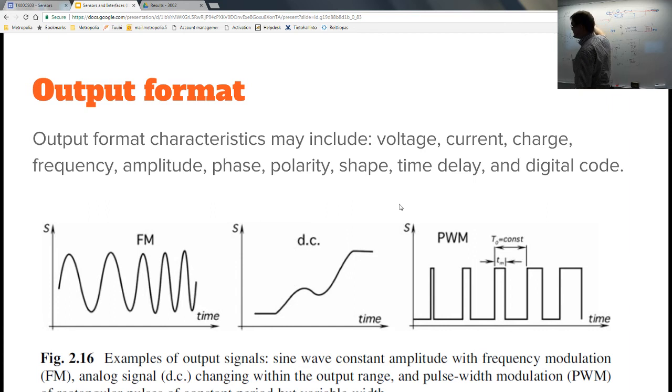And this is the way to do it cheap, since you can have these different capacitors for temperature, pressure, humidity, and then you have just a multiplexer to multiplex different capacitances to one single oscillating circuit, and then you have actually a frequency that you can then modulate with a radio frequency, and there you have radiosonde.